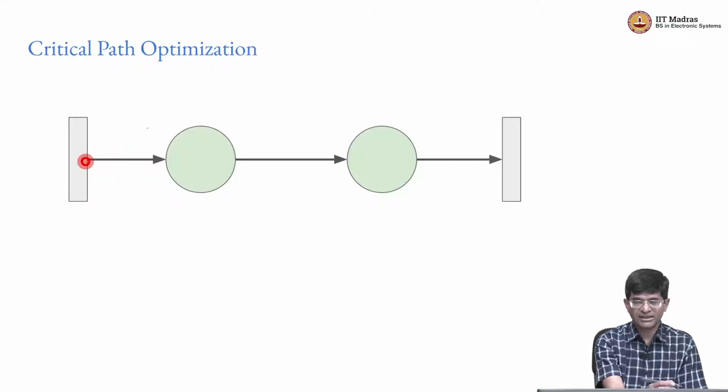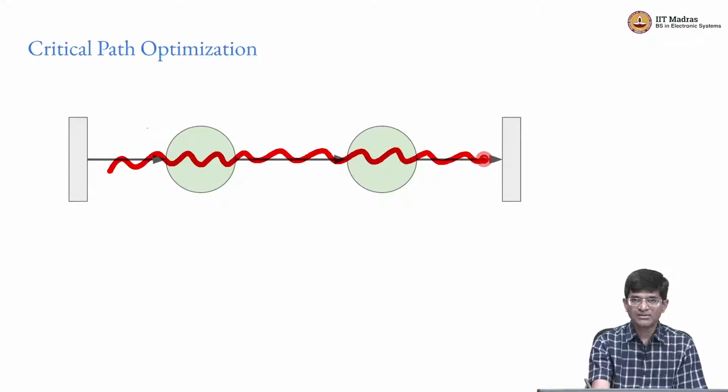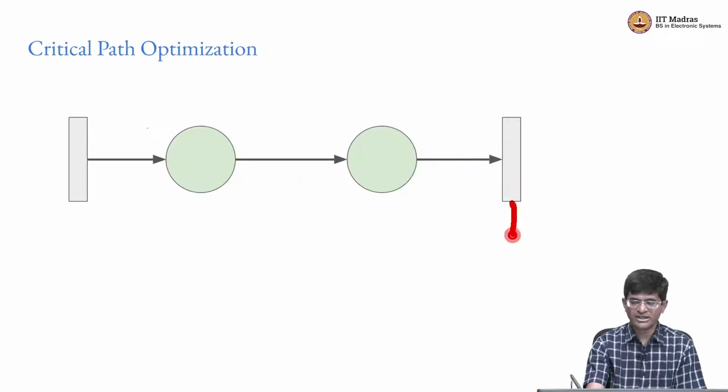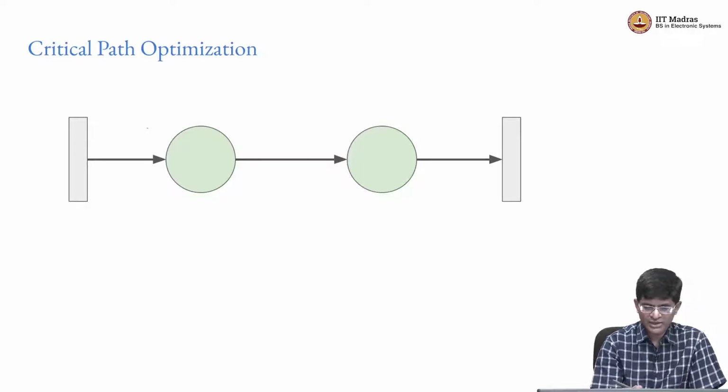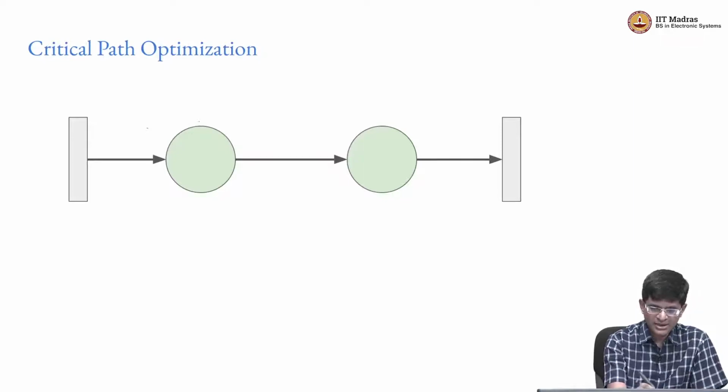That is after all the basic idea of synchronous digital logic. You have a clock signal which basically determines when the signals come out of the register, and from there they can pass through combinational logic and must be ready at the next register at least one setup time before the corresponding clock edge appears at this second register. So the diagram that I have drawn is a highly abstracted and simplified version of what we are trying to do here. Now let's look at what we would actually end up with,